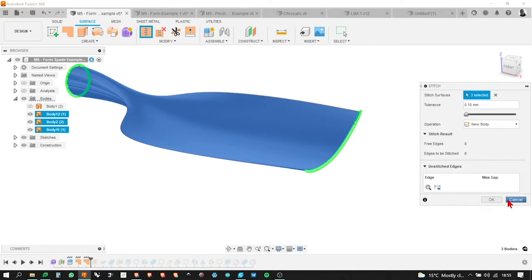Generally speaking, if you've created your features, your surfaces by patching, you're creating them from existing geometry, so it should be correct, unless there's an overlap, a tiny overlap, or a slight inconsistency in the body you're patching from. And it could be quite minute with surface modelling. Let's get solid modelling. Sorry.